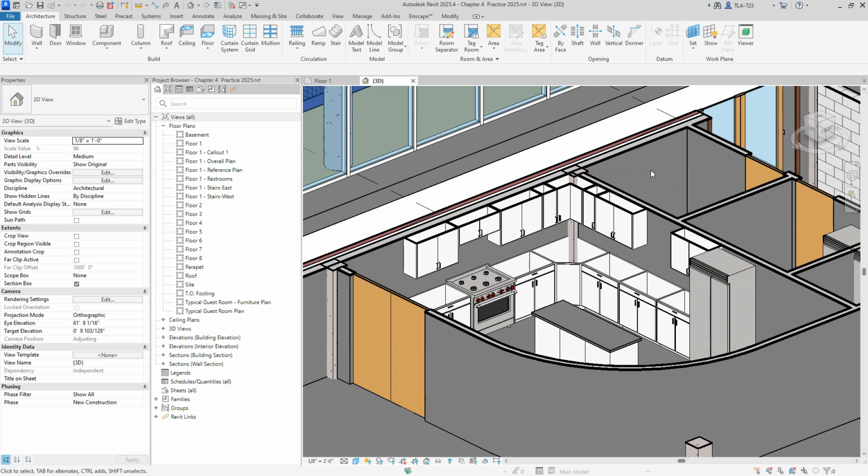And where that becomes important is when we have to fill in a wall-to-wall distance. Now, we didn't do that in this case. We have an L-shaped kitchen, but in a lot of cases, we're going to have a U-shaped kitchen, and at least one of those walls is going to be covered all the way from corner to corner with cabinets. And so making sure that that math comes out right is important. So the concept to remember there is that if you add up all the cabinets and it's divisible by 3 inches, that is a good width to set for that corner to corner distance.